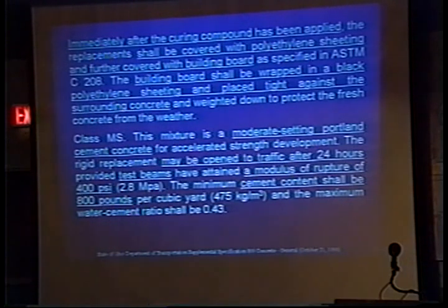The other key with this particular method is immediately after the curing compound has been applied, and I'm going to talk a little bit about curing compounds in concrete work. That's the biggest fallacy I see out there by contractors and by folks doing it themselves. They don't understand the importance of curing. Once you get the concrete placed, you got to keep the moisture in it. You don't want to let it dry out. And that means immediately after you get the finish put on it, you got to cover it up with something.